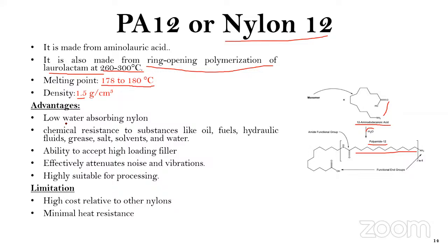Here, like nylon 11, this nylon 12 also has low water absorption, and they are also quite resistant to oil, fuels, hydraulic fluid, grease, salt, solvent, and water. And they can accept higher loading of filler. Suppose you want to add some heat stabilizer or something else to improve the properties of this nylon 12, they can sustain quite a higher loading of filler.